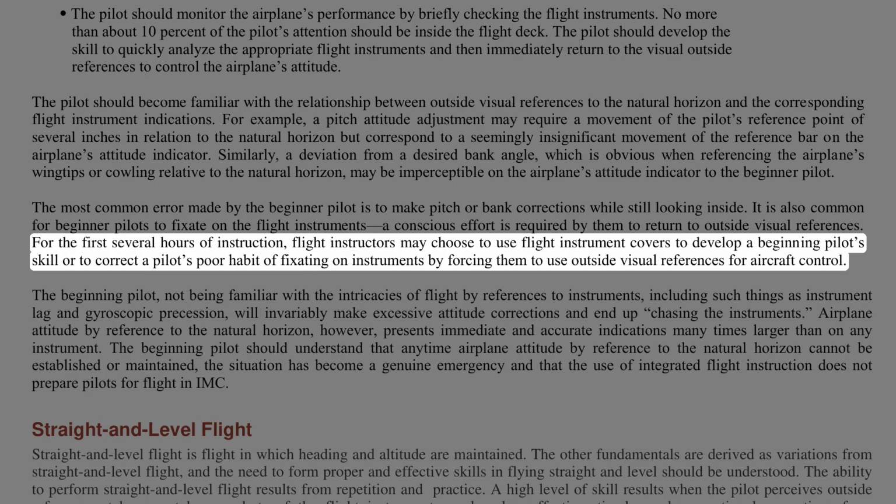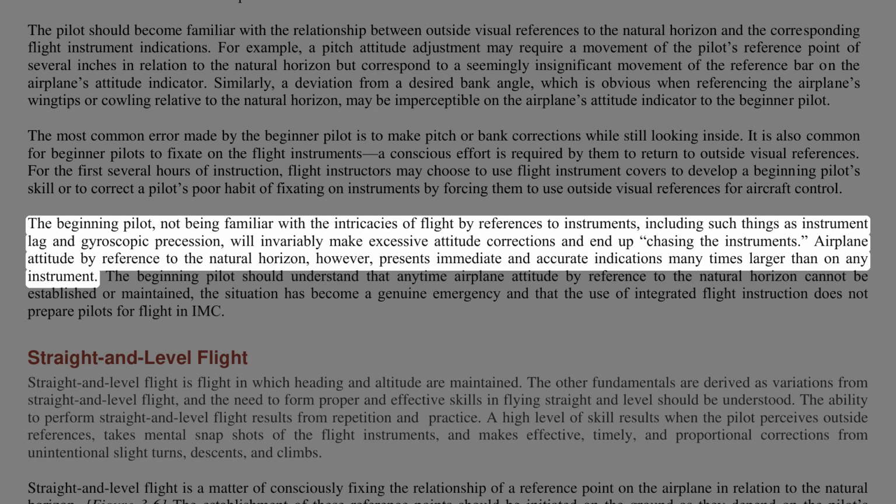For the first several hours of instruction, flight instructors may choose to use flight instrument covers to develop a beginning pilot skill or to correct a pilot's poor habit of fixating on instruments by forcing them to use outside visual references for aircraft control. The beginning pilot, not being familiar with the intricacies of flight by reference to instruments, including such things as instrument lag and gyroscopic precession, will invariably make excessive attitude corrections and end up chasing the instruments.